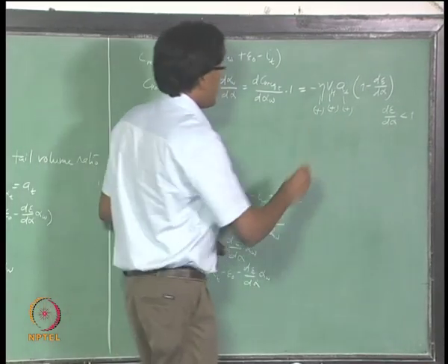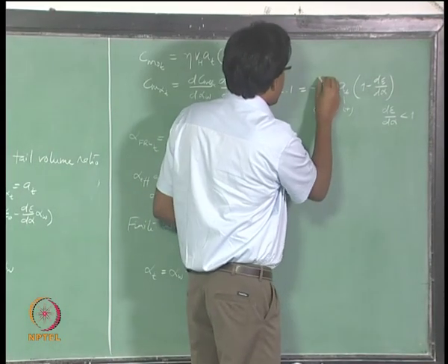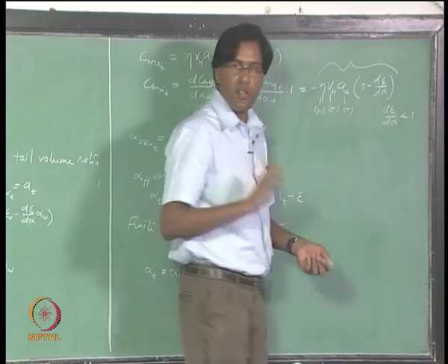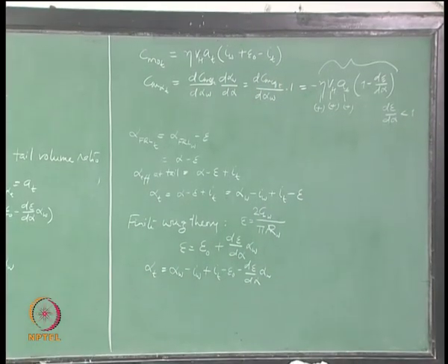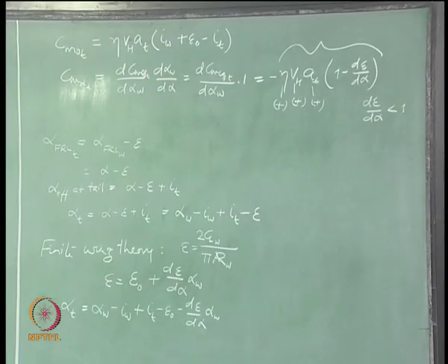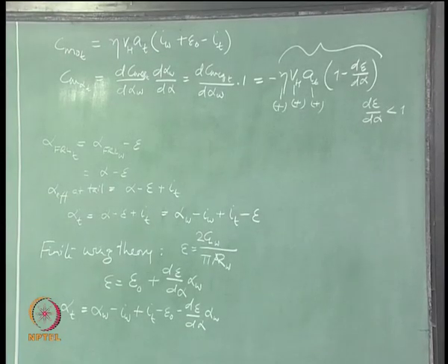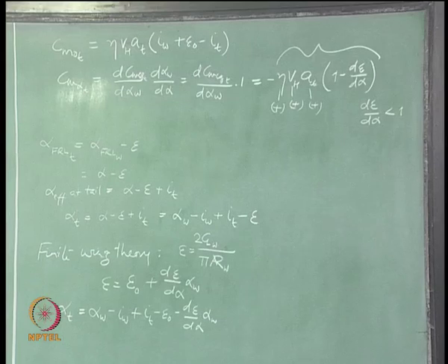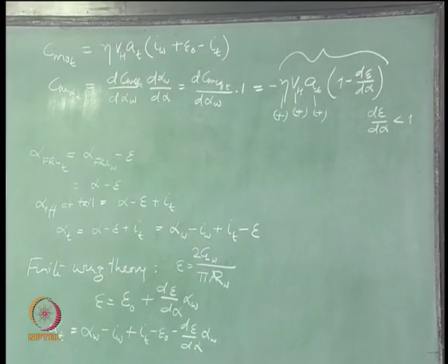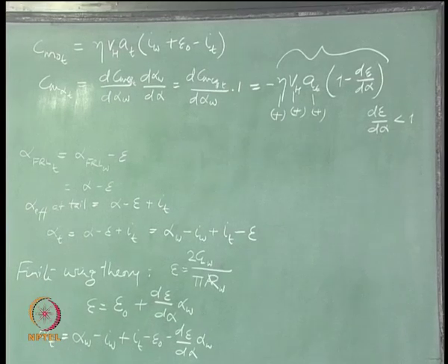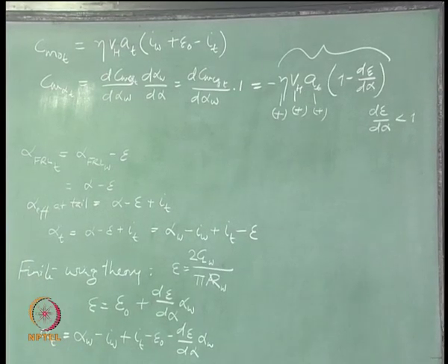So, overall you are going to achieve what you started with, you wanted to add a tail so that you can get the Cm alpha curve for the airplane to become negative, right. For the wing alone configuration it was coming out to be positive, the slope, right.